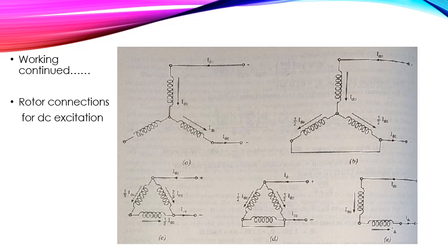The rotor slots are made fewer, means less in number, and larger in size. So these machines are provided with heavy rotor winding in order to have a low starting current and slip, which facilitates in pulling it into synchronism.